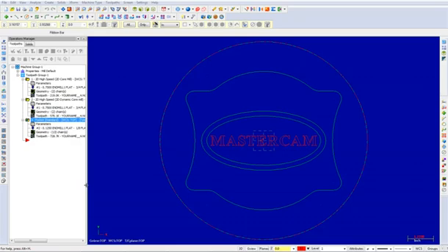In this video, we will remachine the pocket and post the file. Pocket remachining is only used with closed chains. It calculates areas where the pocket roughing tool could not machine the stock and creates a remachining pocket toolpath to clear the remaining material. Like the previous operation, select Toolpaths, Pocket.